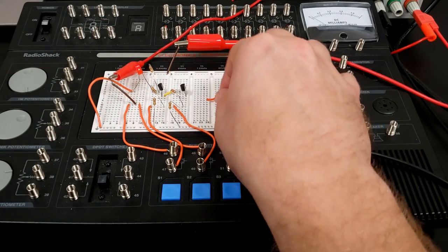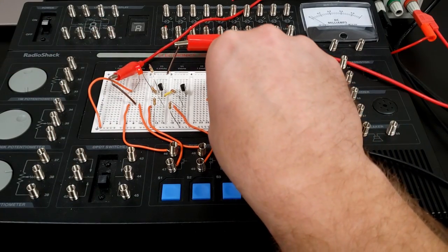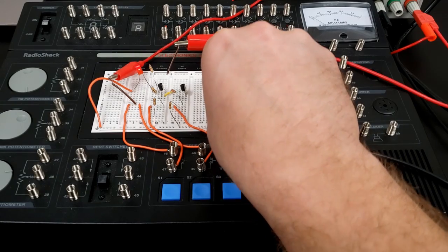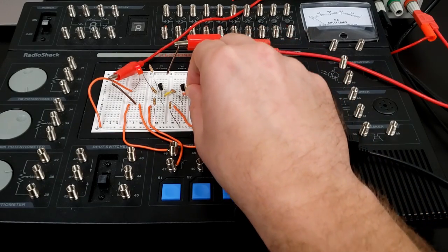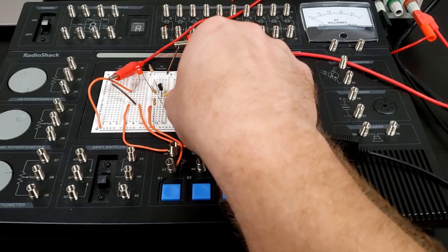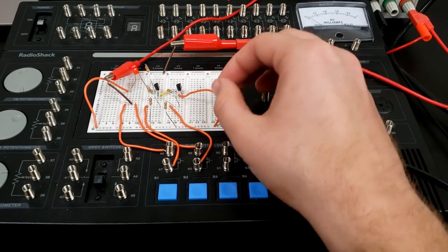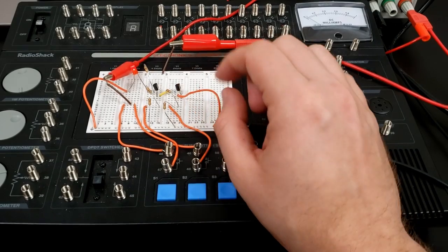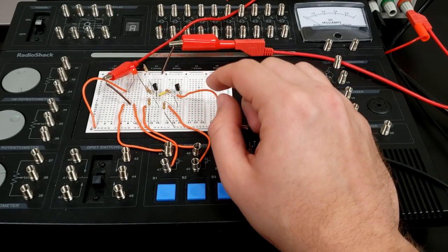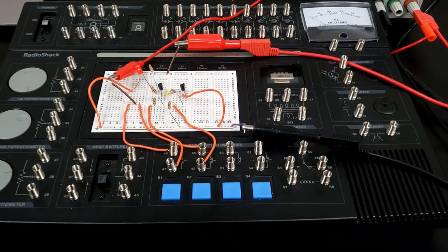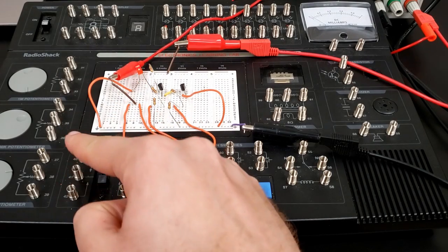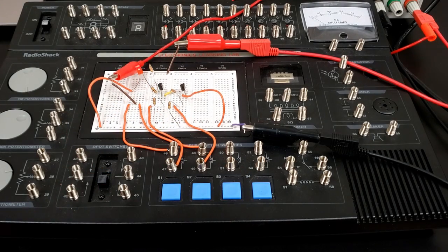And then we want to take where the LED was, and now just run this wire straight to ground. So we took out the LED, put this wire that was connected to the LED straight to ground, and then we moved the LED to point A within our circuit and ran the other end of that LED to ground, as the instructions tell us in step 3. All right, now we're gonna go ahead and do step 4, the final step in part B, and get our truth table.